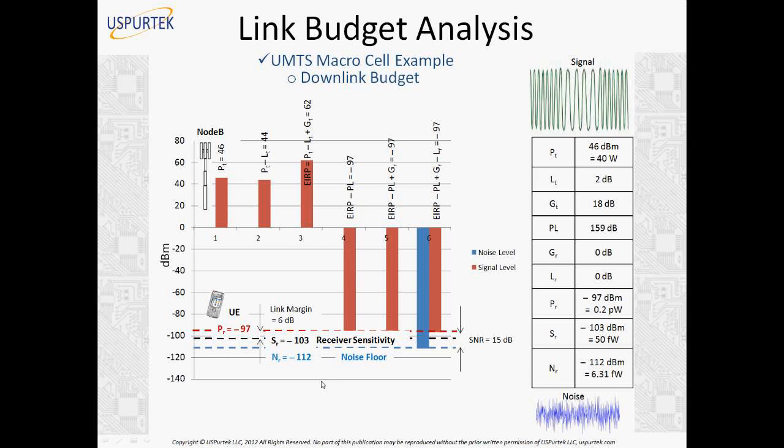Now in this situation, when the link margin is lower, what can we do? There are several solutions we could use. One is a very simple one: reduce the range of the cell. From our calculation, we find that for 8 kilometers distance, our signal level is very weak, and no handset can deliver a reliable quality of service. So then we say, okay, it's not 8 kilometers, it's 6 kilometers or 5 kilometers, and we'll have another cell after 5 kilometers. That is how RF planning works. We have to calculate what the received signal power will be at the edge of the cell, so that we can define our boundaries for the cell.